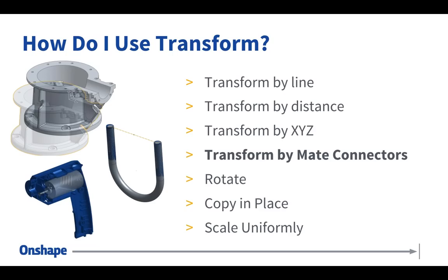This is another frequently asked question that I get. Can we scale parts in Onshape? And the answer is yes, absolutely. It's in the transform command. You'll see a command called scale uniformly. And I'll show you an example of this in just a bit. But these are your options for the transform command. I'm going to walk through as many of them as I can in the time that we have.